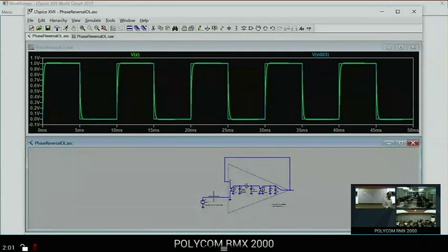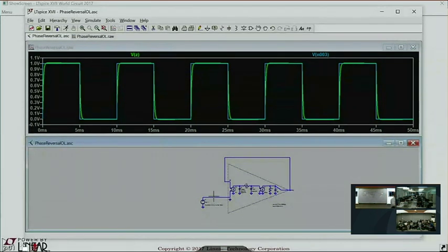Yes, it has the wrong phase, but it's been amplified so much it can't recognize the output as the input, and that's why it's stable. Now, there's an interesting thing. If you transcribe this correct time domain picture to the frequency domain, for something to oscillate, the phase shift has to be exactly 0 and exactly 0 dB gain shift, or it cannot oscillate.